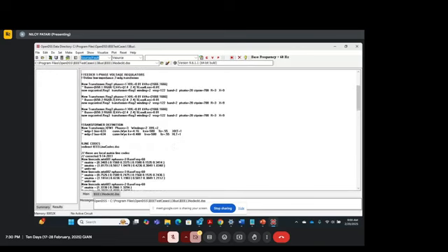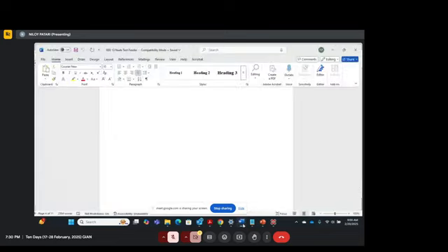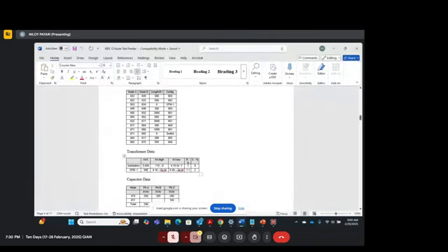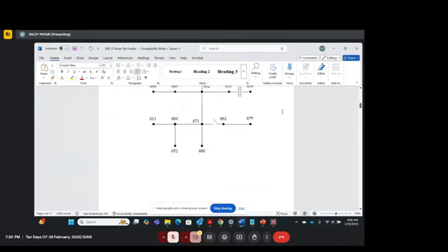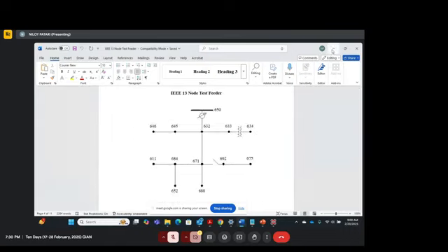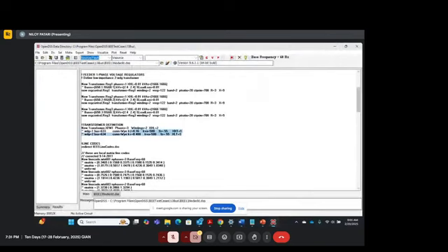And there is another transformer which was present here, right? The 500 kVA one, which was present between nodes 633 and 634. This is again defined here. So you have to define all these elements. Whenever you see this exclamation sign in front, it means that it's commented out. It's exactly like writing percent in MATLAB, or putting a hash in Python. So if you want to comment things out, you have to put this exclamation sign in front.